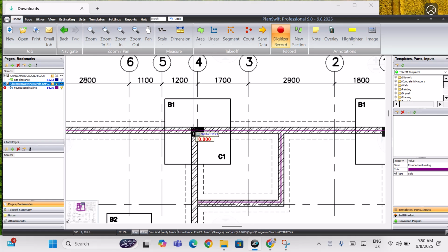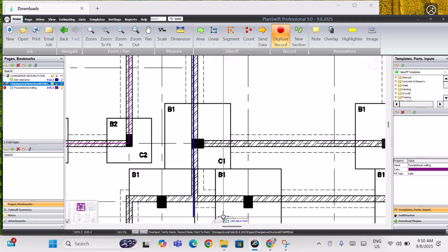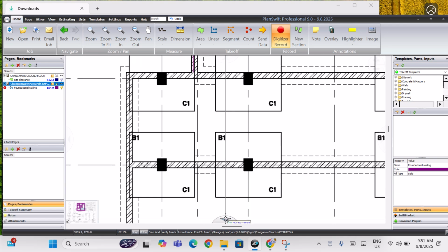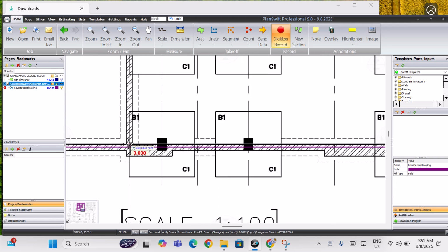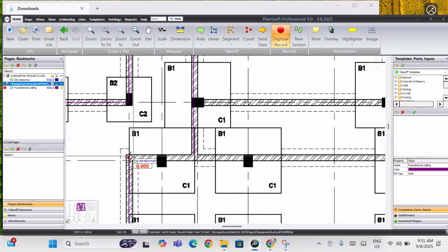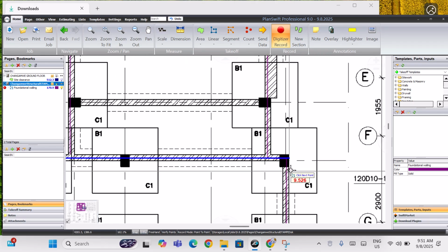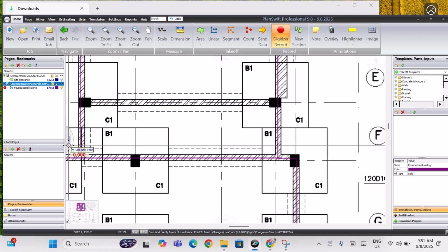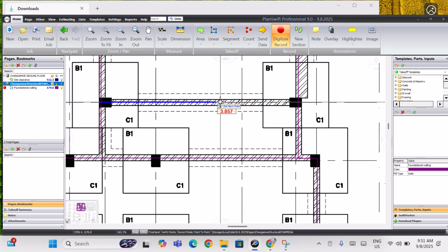That helps to avoid double measurement, which will bring an error when you quantify. And you go up to there, you go there, then you start a new section there, and this part wasn't measured yet, and yeah, it's a right turn there. As you can see, we had already measured up to there. You right click again, new section, start there, done, new section again.